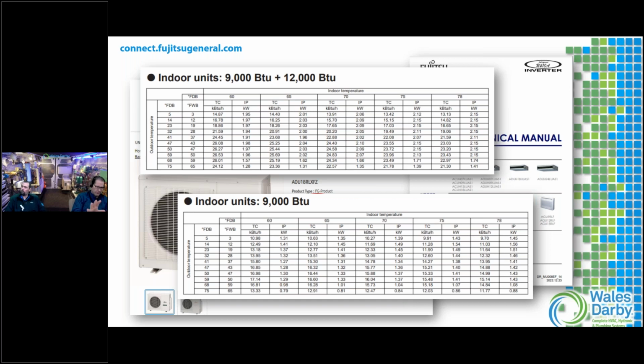So two things with Ray. One, I've never seen cooling and heating loads that close. They spread out a little bit. So if you're trying to cover the heating load and your cooling load is much less, you're grossly oversizing, and that's a problem in the summertime: short cycling, more on-and-off, things go wrong.